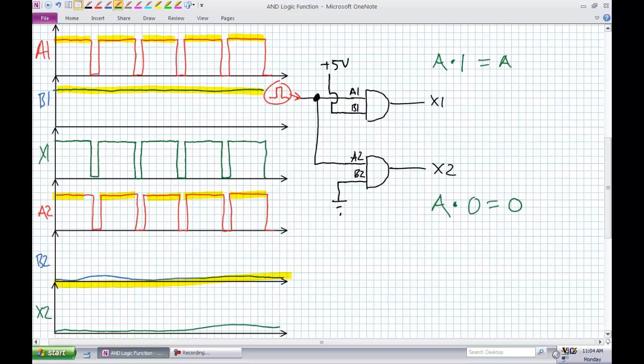So this is a really cool application of an AND gate. We're already getting to our first applications here. What about using an AND gate as a gatekeeper? Basically you enable something, you turn something on or turn something off. What are you turning on or off? You're turning incoming data on or off. Think about this: AND gate, here's my output. Here is some incoming digital data stream. It could be from some sensor or whatever. Here is my enable pulse. When enable is 1, I'm sending that same data to the output. When enable is 0, what am I sending to the output? Straight zeros.